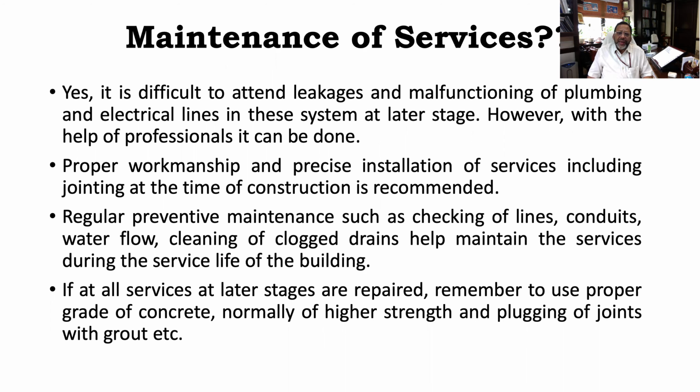So while laying services, always remember that it will be difficult to do the corrections or to do the maintenance at a later stage. It will be difficult. So proper workmanship and precise installation of services, including jointing, is very important at the time of construction.